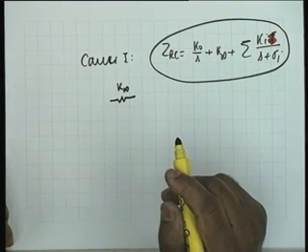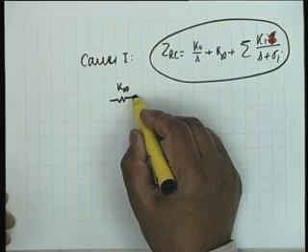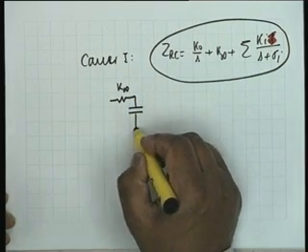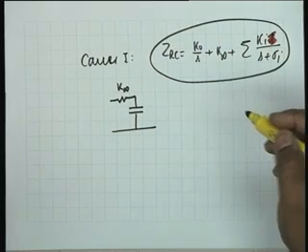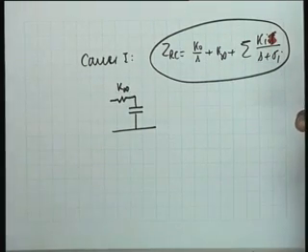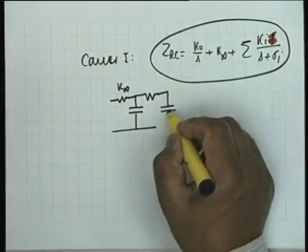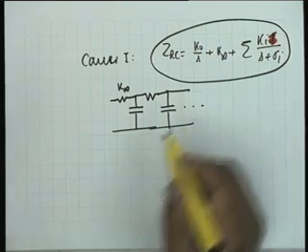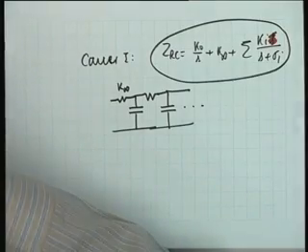It will be a 0, and therefore YRC shall have a pole at infinity, which I can remove as a capacitance. All right. If I remove that as a capacitance, then I take the reciprocal of that function. That will again be a constant, which I can remove, and I can proceed this way till the function is exhausted. That is simple Cauer 1. Cauer 1 simply focuses on the point at infinity.